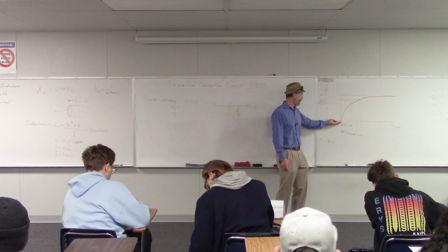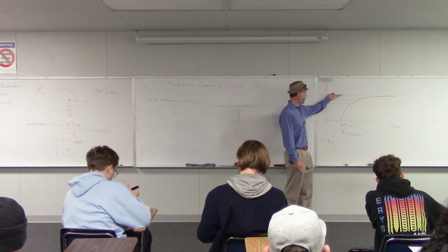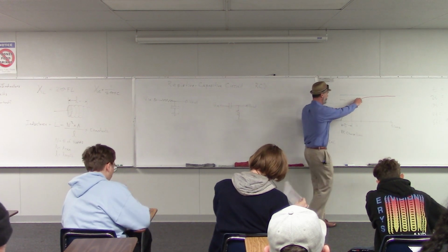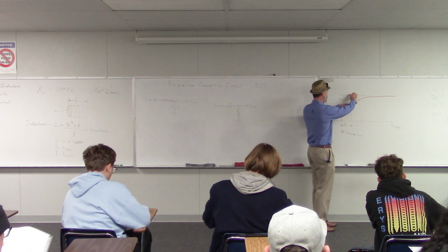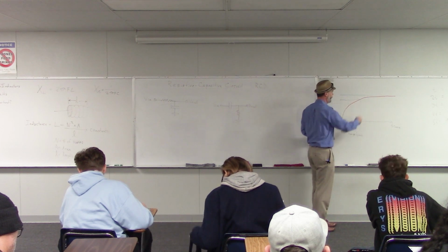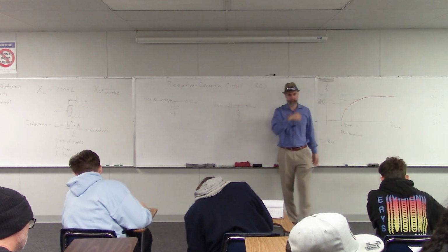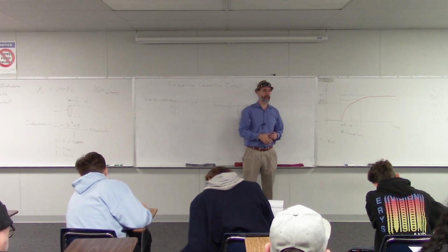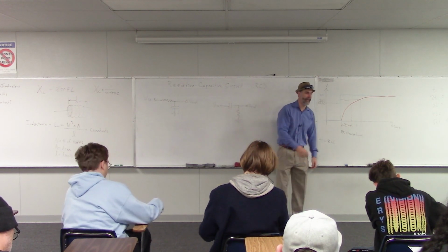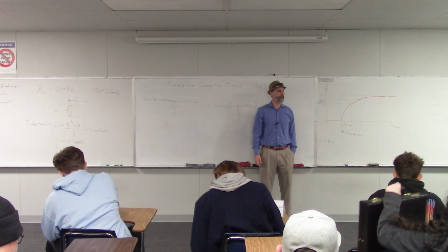So in this first time constant, it goes 63% of the way to the top, and then it ends up there, and then this next one is 63% of the remainder. So that gives you this next value, and then 63% of the remainder, each time. That's a very good point. I didn't mean to interrupt. No, that was one of the questions I always had. Why all these weird numbers, right? Yeah, exactly, that's where they come from. Thank you. Other questions?